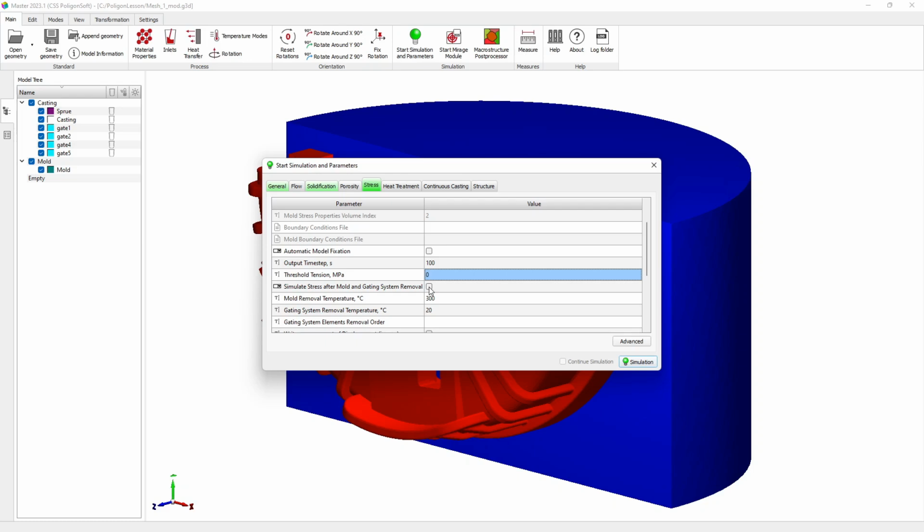task. The casting mold, by its characteristics, is almost like a thermos. It has a very low heat capacity and thermal conductivity. A massive casting cools for a long time and can take 1 or 2 days to cool down. If we try to perform such a calculation, setting the ambient temperature as the stop criterion, very large files will result, and their calculation will take a long time.